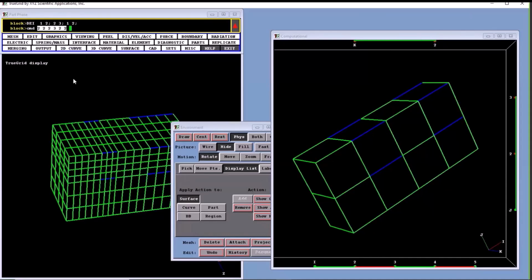We can't. So that's why we have a second type of command with a second type of notation, which is more powerful but more complicated. It's always the trade-off. So I'm going to show you what that notation looks like. But to do that, I have to change my generic command from CMD to CMDI. This is known as an index progression. When I hit F1, because I have the I at the end of this command, it interpreted this command as an index progression command, which allows for more complicated objects like this.